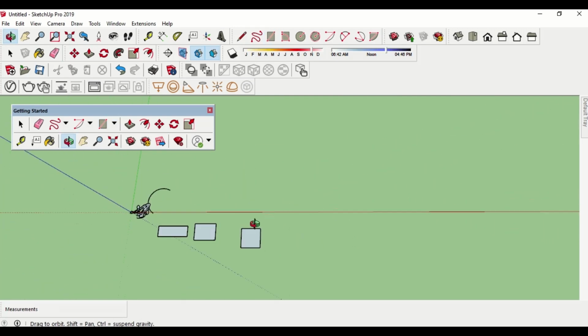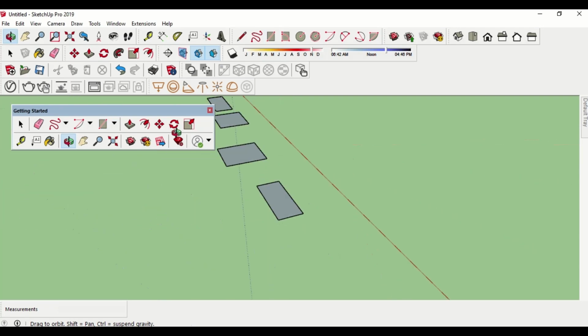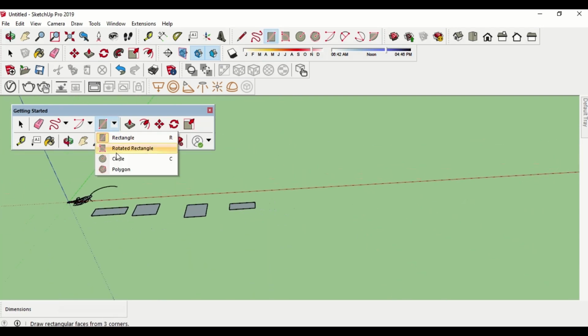Now what if we want a rectangle of our desired dimensions? First we'll select the tool. Our tool is already selected, but we'll again select the tool. We'll click on the screen, and then write over here our desired dimensions. Now we'll write like 500 feet by comma, or comma by, here comma means by, okay, 500 feet by 200 feet, and enter, and see, here's our rectangle.